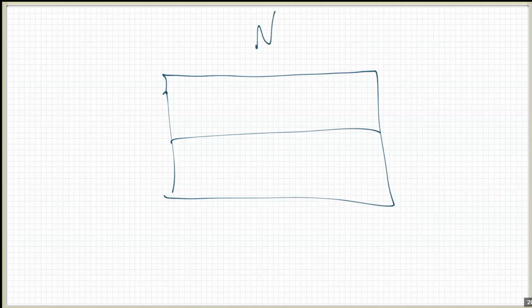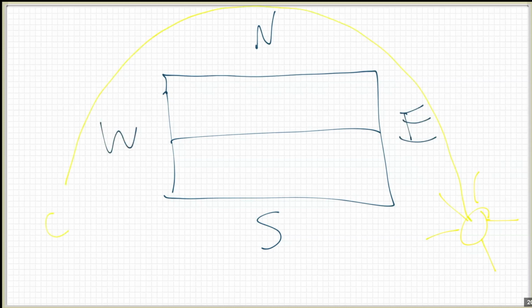If you consider a roof now, here I'm drawing the roof again, but this time I'm going to make north at the top. So there's north and there's south. Depending on your latitude, if you live in southern Australia, the sun actually rises over here in the southeast in summer. So this is east over here, and west, and it will traverse the whole day, go around the north, and then set in the west. So actually in the morning and the afternoon, the sun is in the south.